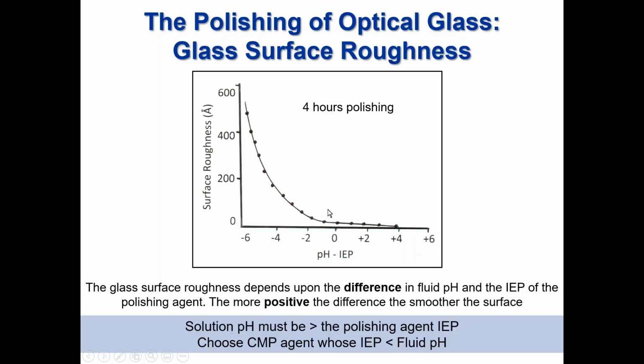This ensures that the polishing agent particles and the glass silica groups always have the same sign of surface charge. The corresponding repulsive electrostatic force then inhibits aggregation of the polishing agent particles and the dissolved silica species in the recirculated slurry. And the finely dispersed slurry remains so and hence produces the smoothest possible surface finishes.